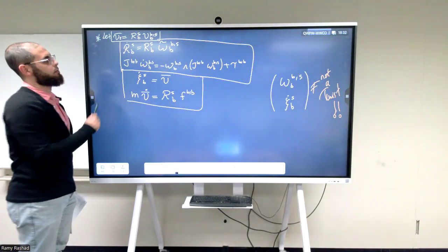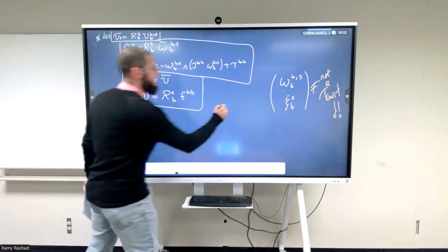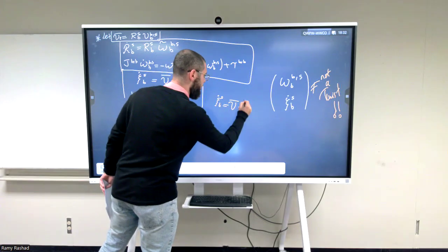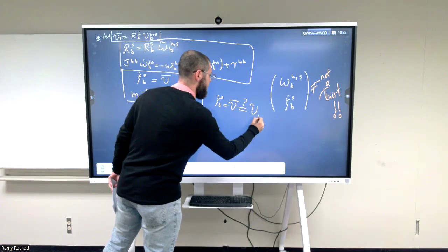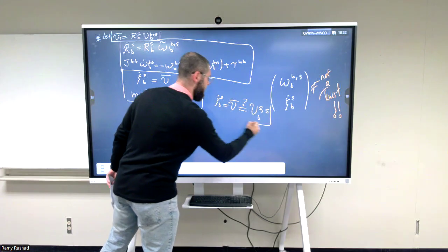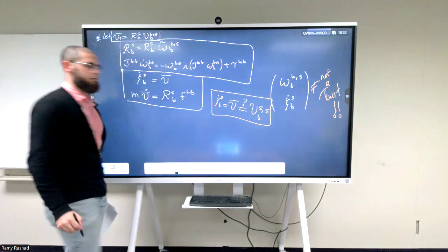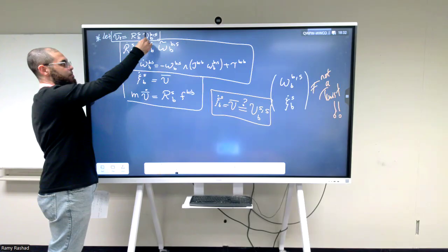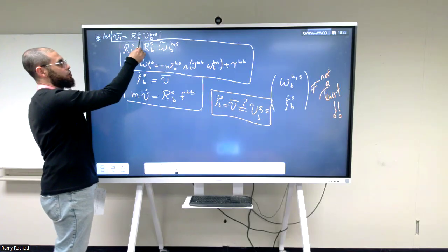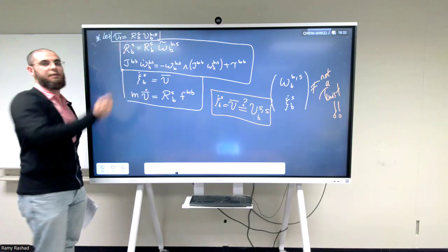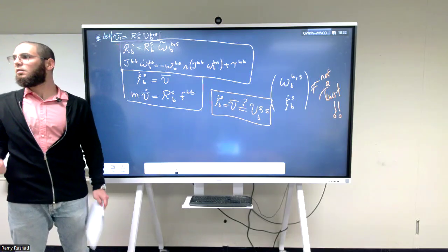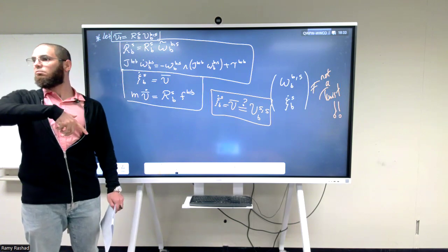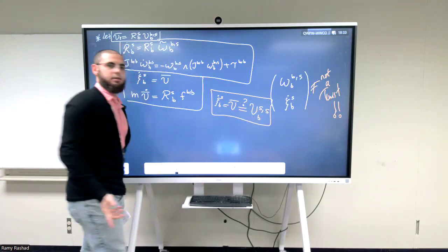You see this V bar? A question to you. Is V bar, which is equivalent to the psi dot, equal to V from B to S expressed in S? You see here, I have V_BS expressed in B. Then I take the rotation matrix and multiply it from B to S, and I say this is the V bar. Isn't this taking the vector B to S expressed in B and expressing it in the S frame? So it should be something like this, right?